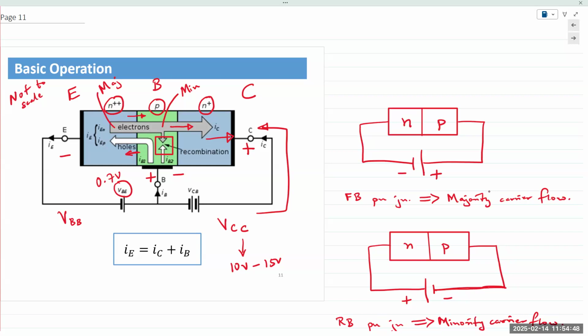And that again is due to the differences in the doping. And when we are talking about changes, meaning we are talking about increasing the base voltage, think about it. Once we bias, once we are applying our DC voltages at the base and the collector, an AC signal that comes in is only fluctuating in the millivolts. So when we talk about increasing or decreasing the base voltage, it's a few millivolts. That's it. We are not applying like 10 volts on top of our DC bias.